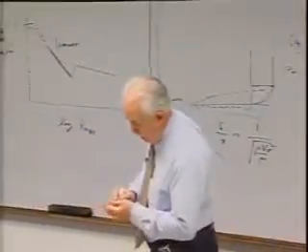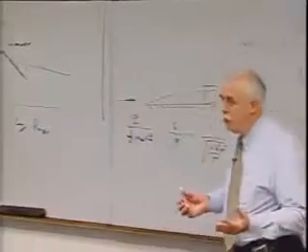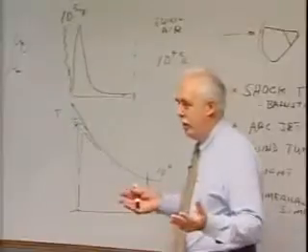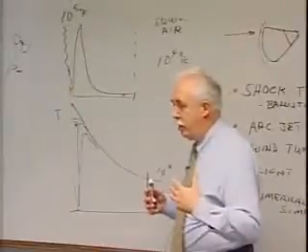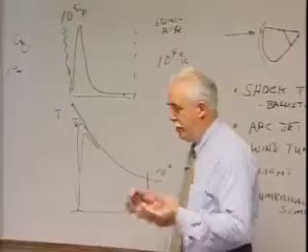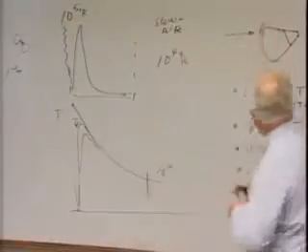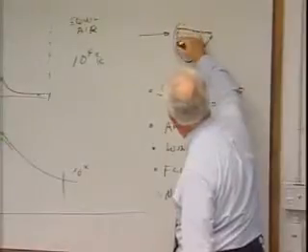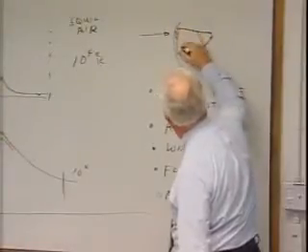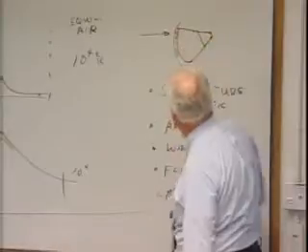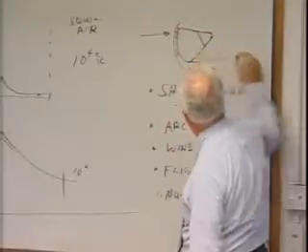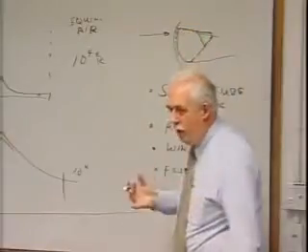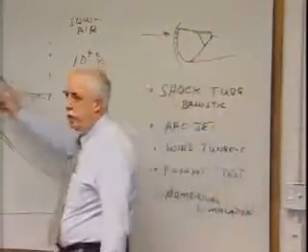On the shuttle, we get into far more complicated geometries, and the major challenge on Shuttle was that three-dimensional geometry. And we did a bunch of numerical simulation development. We had focused on the subsonic region on Apollo, which basically is most of the front side here. About the middle of the vehicle down is supersonic, and then of course you get into the wake here.